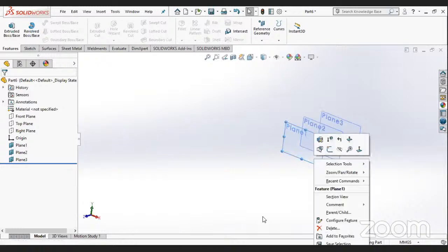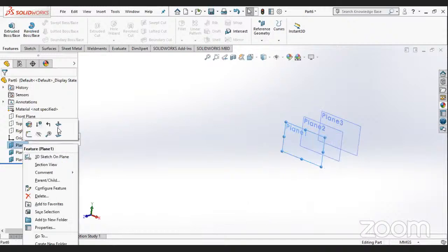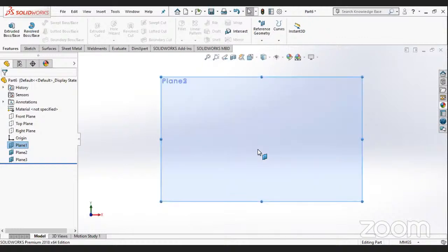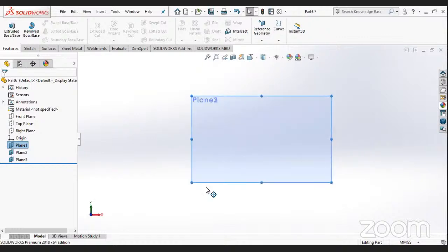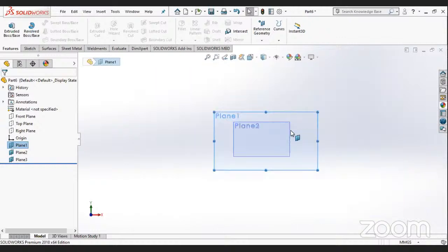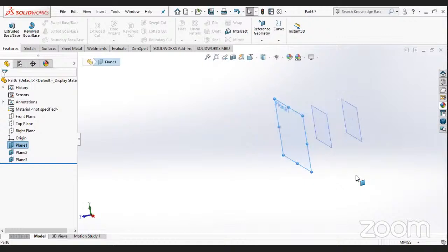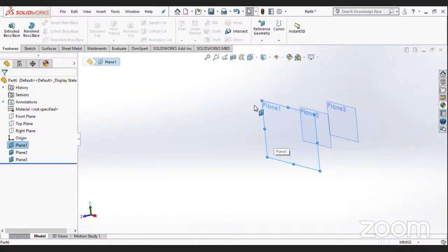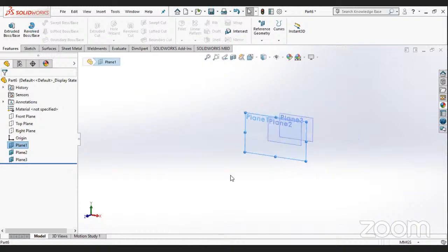One note here, it is not compulsory that the drawing will only come inside this box or inside this plain blue. You can increase this box anywhere and however you want, and the diagram which you will be drawing will be anywhere in this canvas but only on this particular plane. So whatever things I am drawing will not appear in the second and third plane or any other area. It will only appear on this plane. So make sure that you select the proper plane from wherever you want to start sketching. This was about parallel plane.